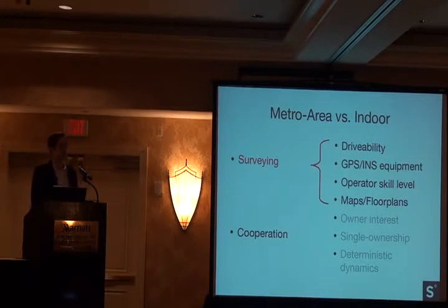In terms of the operator skill level, when you're surveying outdoors, you basically need someone who can drive and follow directions. Indoors, you need someone who is actively aware of what your equipment is doing, just because it's so difficult to make sure that you're associating the right ground truth location with your scans. And finally, the availability of maps and floor plans is different. It sounds like more standardization is happening in terms of the availability of indoor maps, but it's still sporadic. It varies from country to country, city to city, and across different types of venues. Whereas outdoors, we can generally depend on the availability of maps. So all those things create additional challenges to us when we want to move indoors.